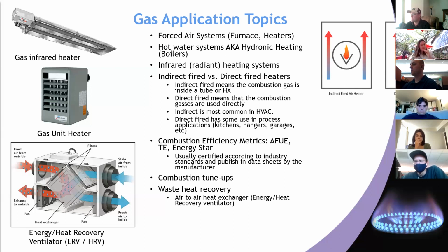The idea is that with stoichiometric combustion of air, you should minimize the amount of air that you're putting into the system to only slightly exceed the stoichiometric ratio that you need for combustion of natural gas. And so that's usually attainable to about 3 or 4%. So in a perfectly tuned system, you'd have about 3 or 4% oxygen in the flue gas coming out.